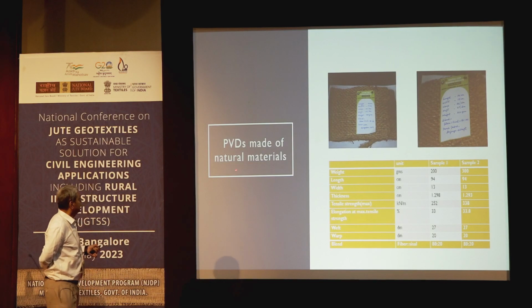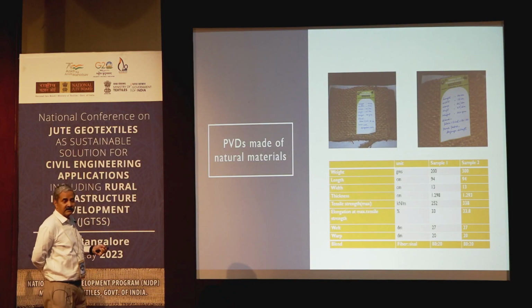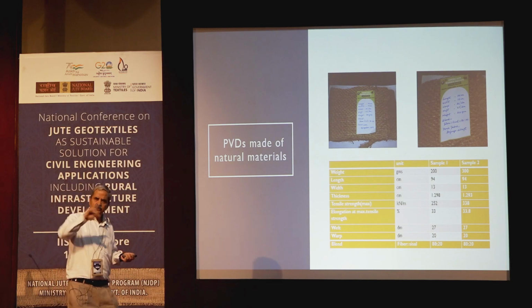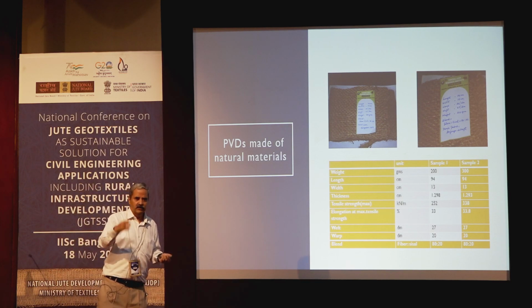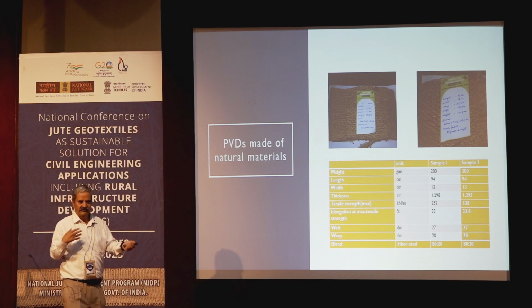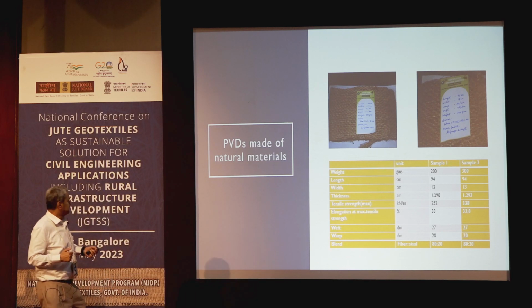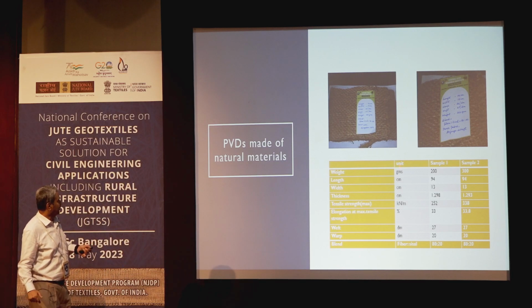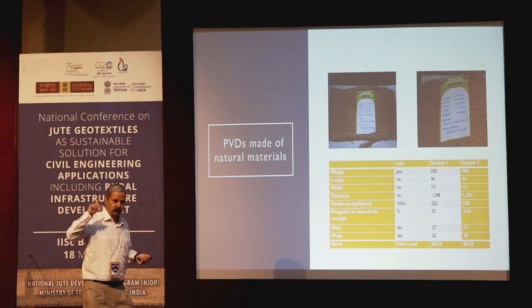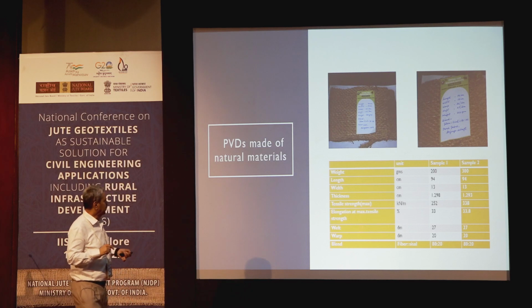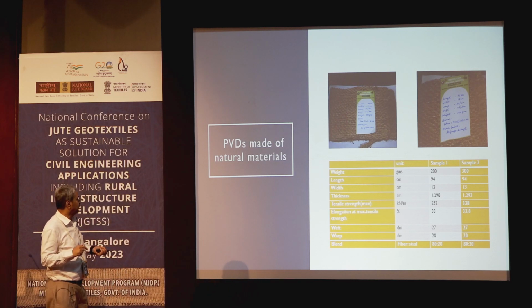The other important point I want to talk about, the other project that I was mentioning, was the use of a combination of different fibers, right? Jute geotextiles mixed with coir, 50-50, 40-40. We did a BTRA project a long time back. This is another thing that I did in IACMAG, like coir board wanted. This is actually a blend of fiber, sisal and coir. And the drains I mentioned, the jute drains. This is a coir drain, and they developed it and wanted to know, can you use it for ground improvement?